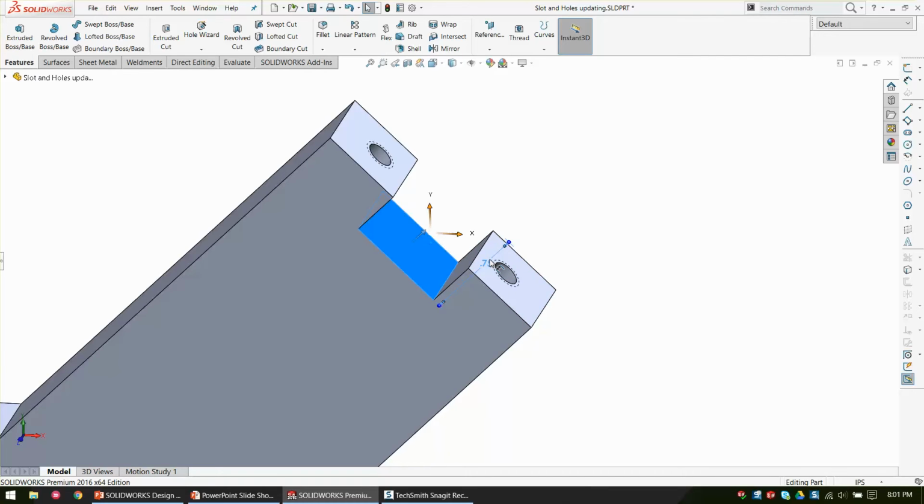But this is a really clever way to model a key, and a lot of people resist it because you're creating extra geometry in space that doesn't hurt anybody. And most people just focus, I need to remove a 1/2 inch by 1/4 inch, so that's what I should draw. But think about it a little bit broader. I'm putting in a keyway. A keyway is square. I don't want to have more dimensions than necessary, and I want single point edits. So I draw in my entire key and cut away that model. It's only going to cut away half of what I draw.